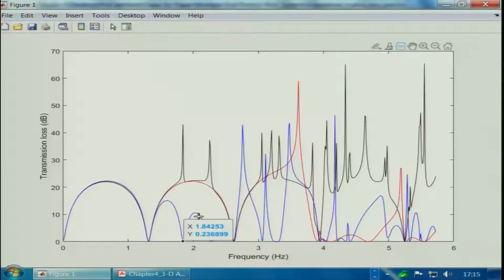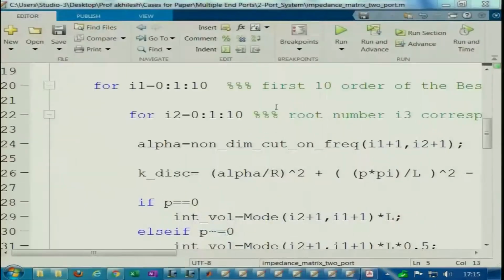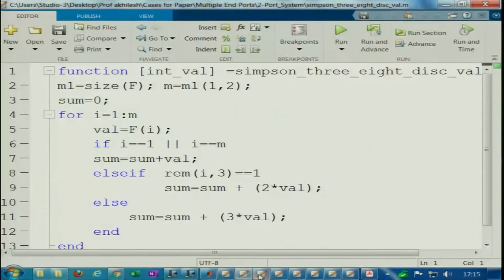Okay. So, if you can at least have concentric inlet and outlet ports, it is still good. If you can have one port offset at a certain location, it is even better, but do not have both the ports offset, although they are both at the radial nodes of the radial mode, but that is not recommended.